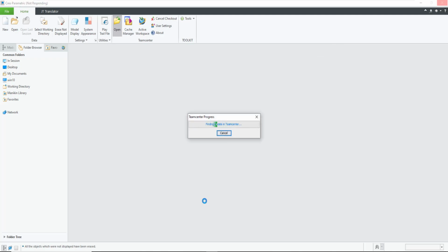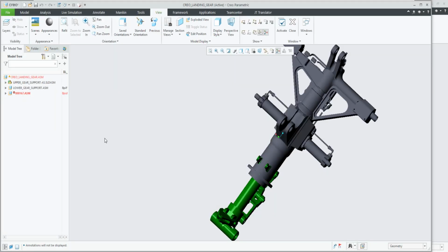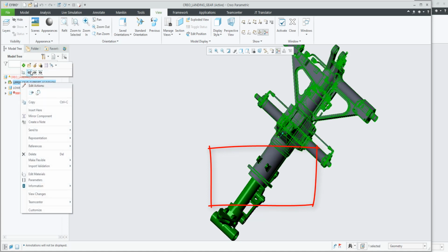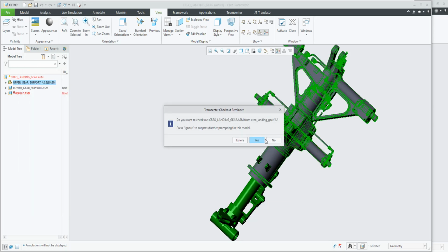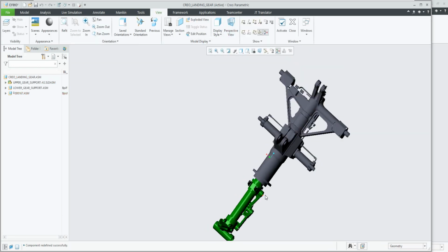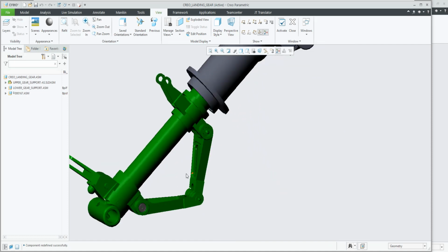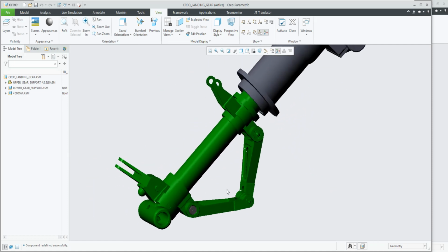When the top-level assembly is reopened in Creo, the changes to both the SolidWorks and the Inventor subassemblies are seen, but the native Creo subassembly is initially out of position with respect to the SolidWorks design. This is because I don't have the additional PTC license, collaboration extension for SolidWorks, to enable the update to happen automatically. The update can be forced by editing the definition of the SolidWorks design.